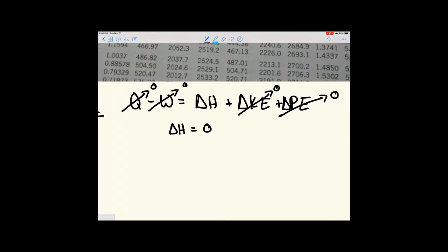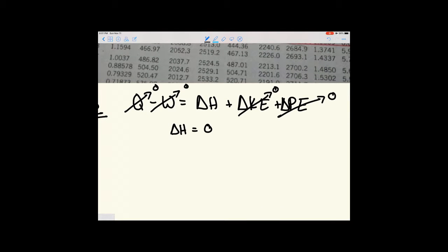Granted, the drawing is a little confusing, but the discharge occurs right before the valve happens. So, therefore, this change of enthalpy will translate into H at point 3 minus H at point 2 equals 0, which then means that H2 and H3 are the same.